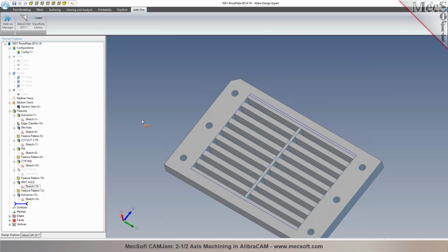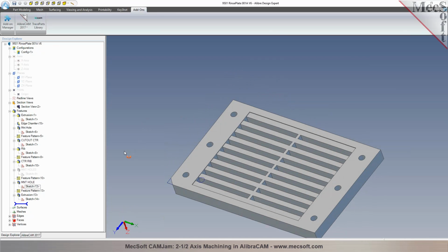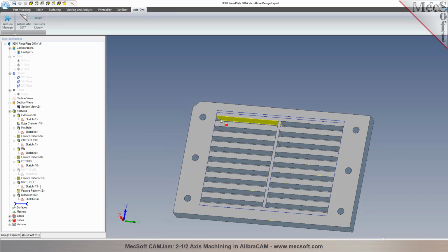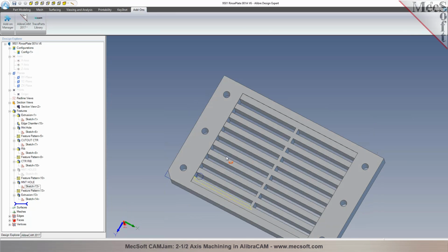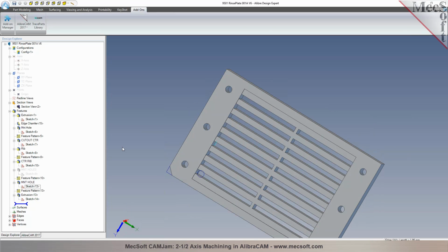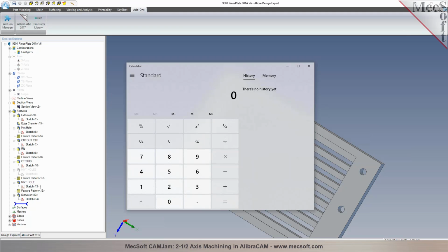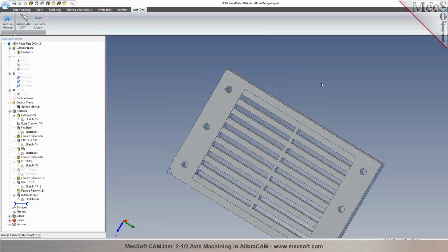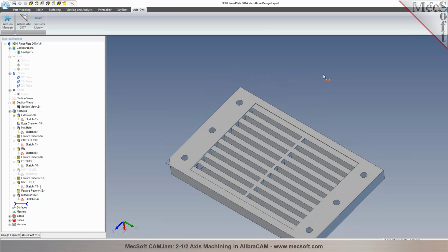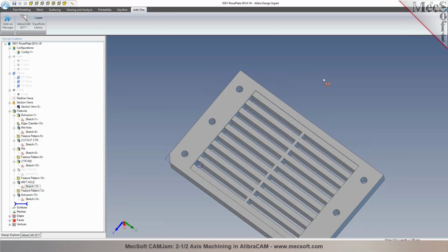We would probably use, I'm trying to think if we'd use an 1/8 inch cutter in there. We probably would. Okay, so if they are 1.95, it would be smaller than an 1/8 inch, right? Yeah, so let me do the math here. 1.95. So that would be 0.62, a 16th. Yeah. So you'd want to use a 16th inch cutter.